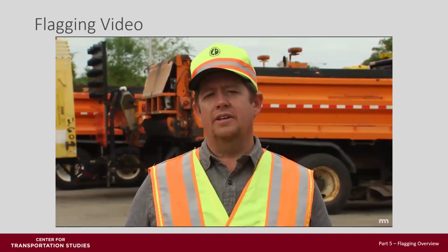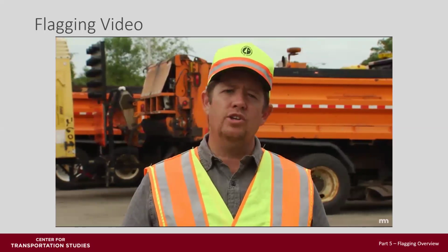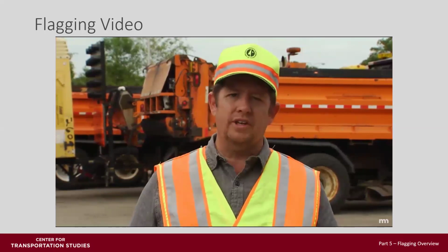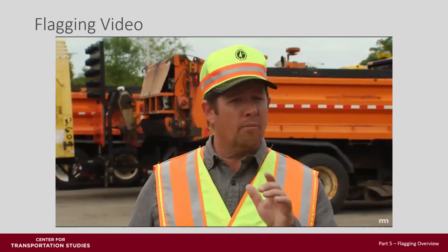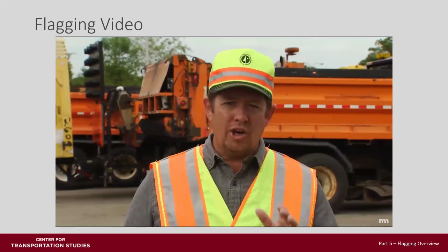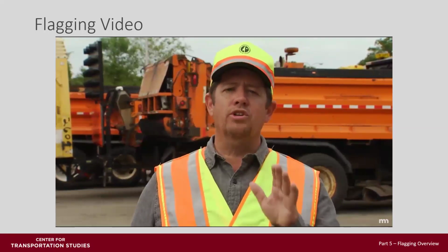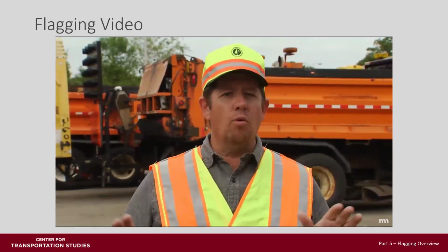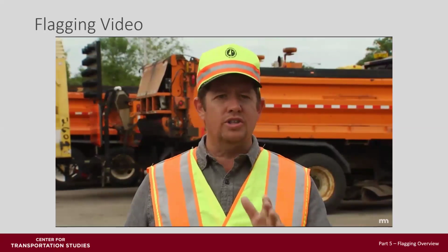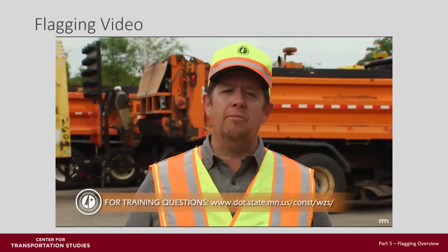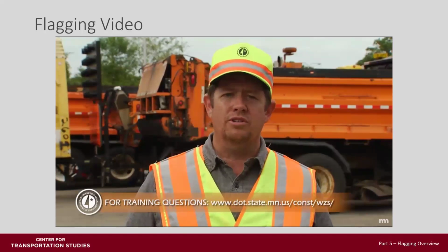Face oncoming traffic. Stand alone in a good visible location away from other workers and work vehicles, and never stand in the path of approaching vehicles. Your job as a flagger is one of the most important jobs in the work zone. Everyone, including the motorists, fellow workers, and you, will depend on your ability to properly follow these flagging procedures.